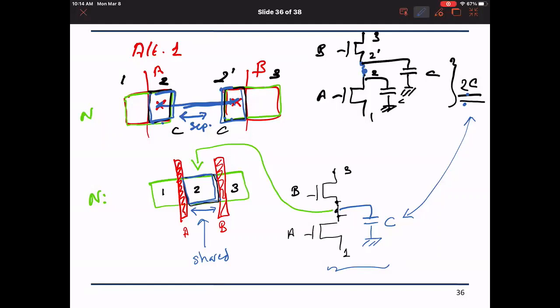What you will see is that later, as the transistors become more, you will need to find if a Euler path exists, and you need to find the common Euler path. Here I knew that I have to go through A B and connect them, but later I will not know really what order unless I visit them through that specific order.